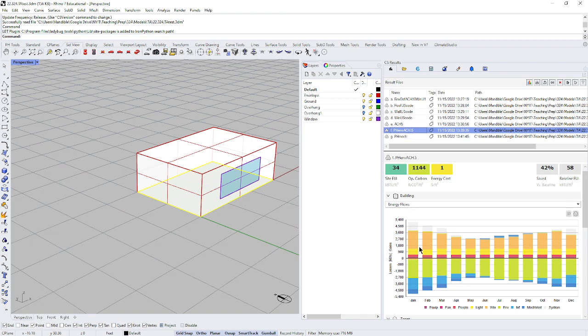When we're here at passive house level, then adjusting this becomes very important. The orange row, and we still have a lot of infiltration, even with 0.5. I noticed that their default, I think, is 0.1, which is possible, but that's pretty difficult to do.